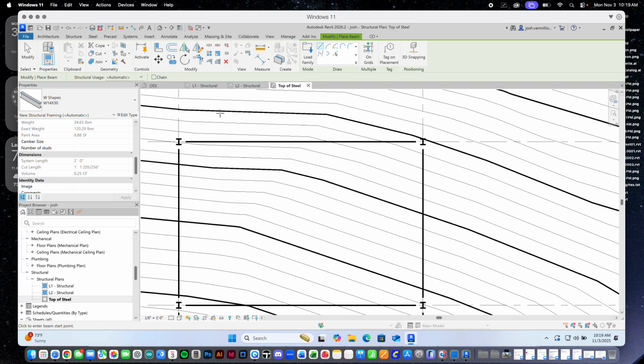You know, I wonder what the snow loads on Mount Charleston are. They ought to be fairly substantial from time to time. You've got wind loads, lateral loads, right, from the wind, shear and moment from those, but also dead loads of snow, right? Because you get the piles of snow, that's ice and water. So yeah, we can't skimp on these beams. In other words, we'll go ahead and keep them as W14s.